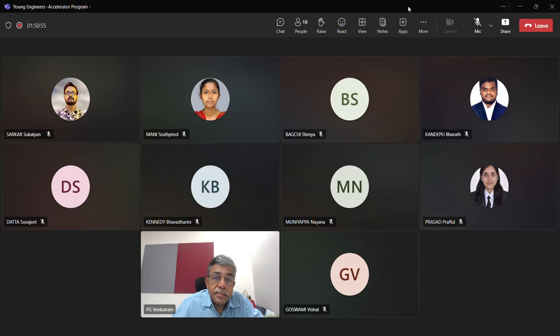Anything else? If you take a look at your IRC SP 114, you will notice that it is asking you to do the free vibration analysis of the superstructure using standard structural analysis software. And please understand, it only says the seismic zone factor for vertical ground acceleration may be taken as 2/3 of that for horizontal motion. What does it mean? It says modify Z.